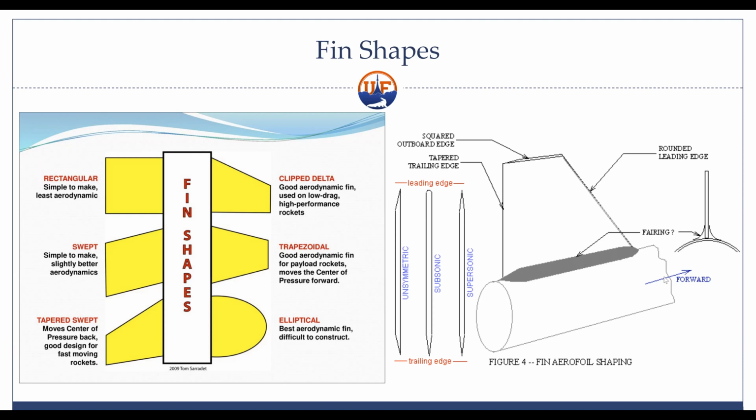So very important things to consider. The fillet, for example, also adds additional cross-section area. So you're sacrificing your drag, but you're increasing a lot of the structural strength. So it's not all about how do I make this thing go as fast as I can? You also have to consider how do I not have a rocket turn into a missile? So very importantly consider that.